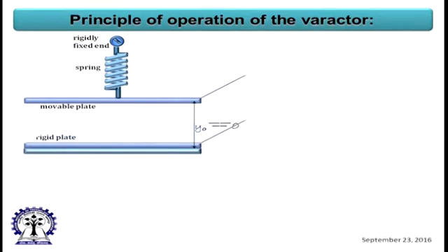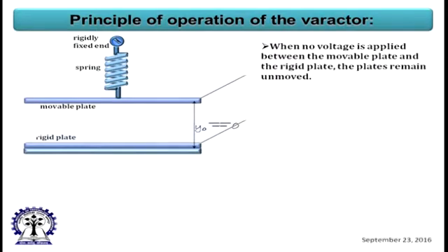So that capacitors being on-chip, can we make mechanical capacitors, miniaturized capacitors, and that quality factor will be much better? So with this vision, we tried to develop something that is called MEMS-based varactors. The idea is that you have 2 parallel plates, and if you apply the voltage, then this parallel plate will be pulled down.